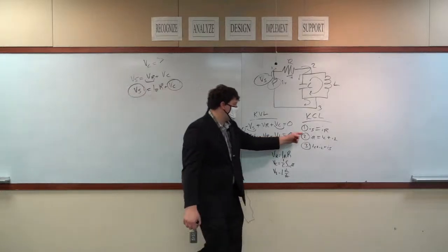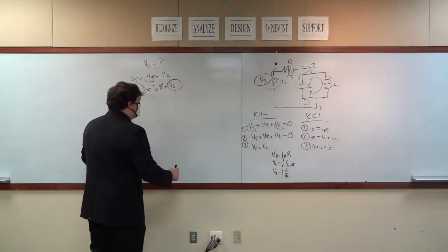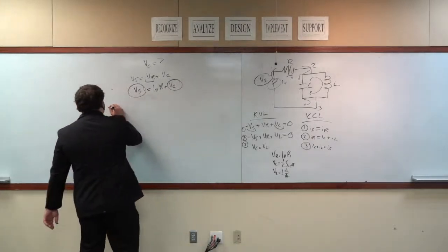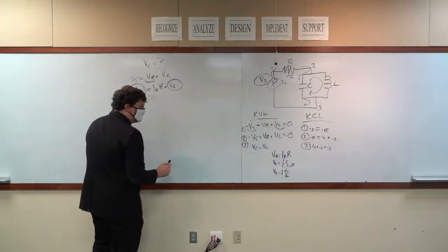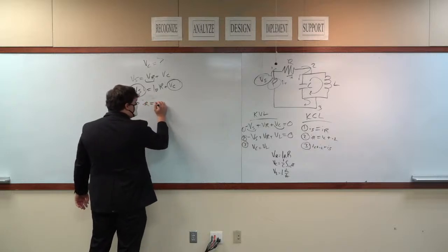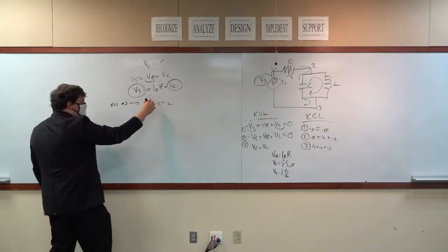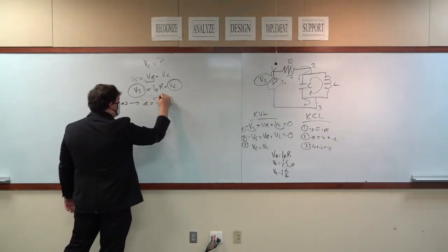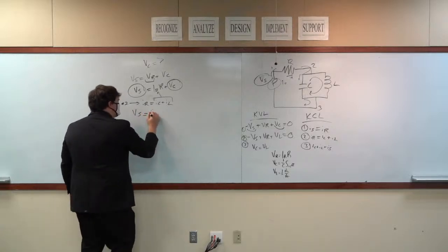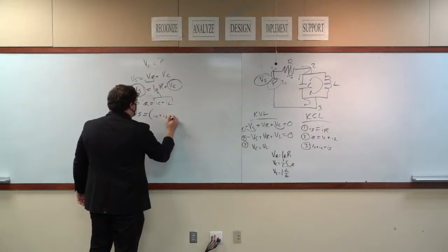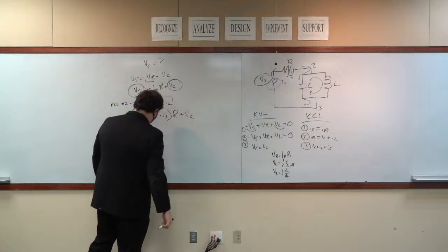We got the KCL. We have this one right here. We have number 2. Okay? So if I say KCL number 2, I'll just go ahead and write that. IR is equal to IC plus IL. We're going to go ahead and interject that in. We will replace IR with that formula, and we get VS is equal to IC plus IL R plus VC.